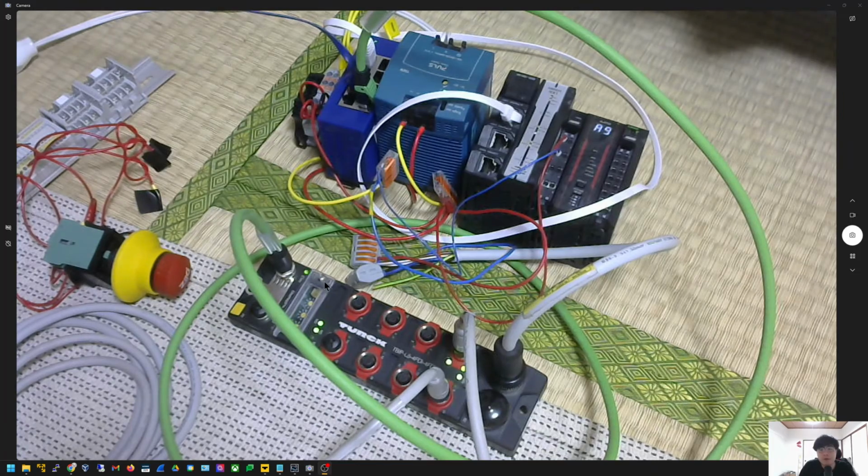If you have used Ethernet IP before, you know all the LEDs have meanings in CIP. In the CIP standards, they standardize the meaning of each LED. Here you see MS and NS are steady on, not flashing, not red, so it means the safety connection is okay. And also on the OMRON side, you see here for the SL5700 that it is showing 8 line something.